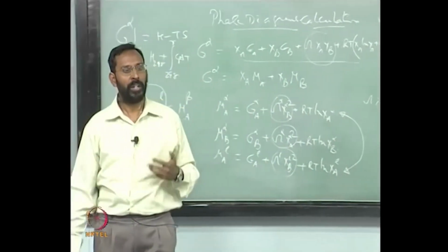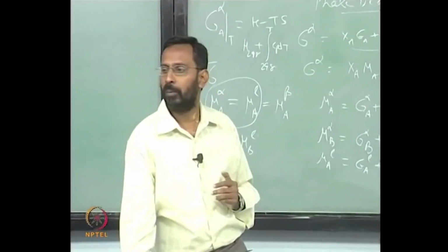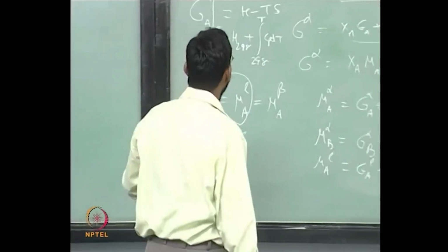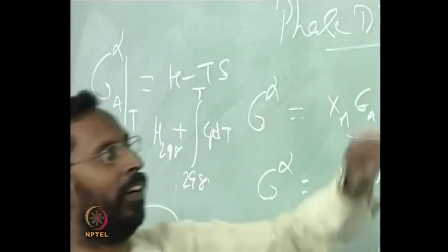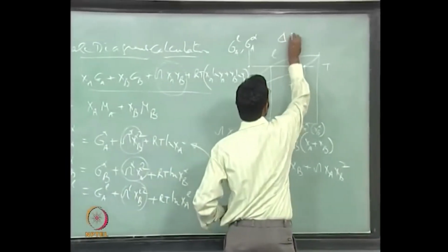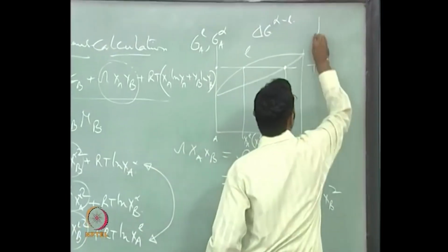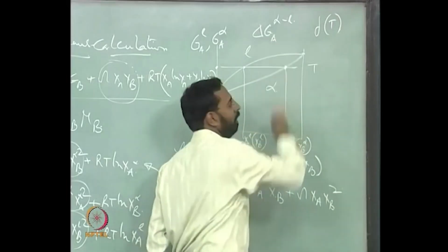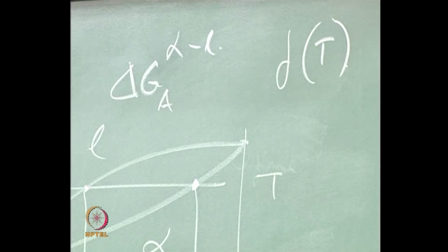That is where you need to use various thermodynamic models that are available, which we talked about in one of the classes, where we talk about the change in the free energy between alpha and liquid. If I know delta G alpha to liquid as a function of temperature for a given metal A by some model, where there are various models, one such model is Turnbull's model.